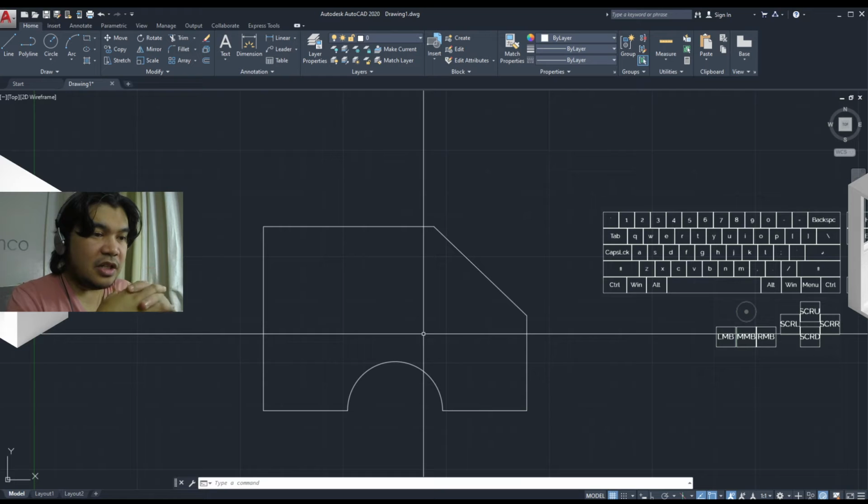That means it has to have arrows on it and or architectural markers that delineate the end of the dimension and the beginning of one other. And like text, dimensions also can be styled, and the command for that is a very simple letter D, which will bring up the dimension style dialog box.